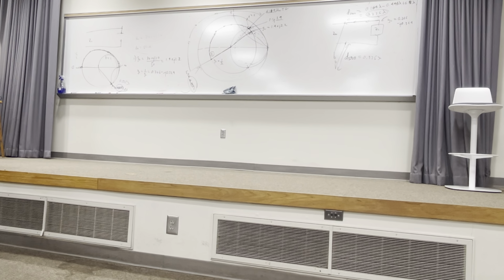And here's the other thing. This is for one single frequency. Only one frequency. As the frequency goes up, the wavelength shortens and the line length shortens. Then you're not matching exactly. When you're transmitting, you don't transmit just a single frequency, usually. You have a modulation index where there'll be a bandwidth. And so there'll be variance in there for the amount of matching. So you just have to be aware of all these things.